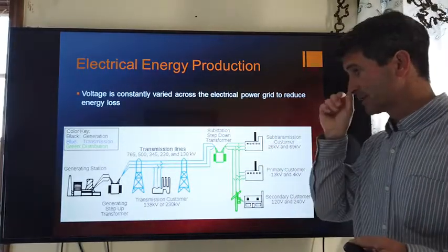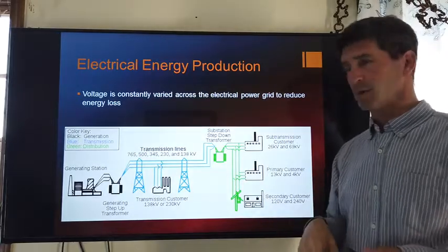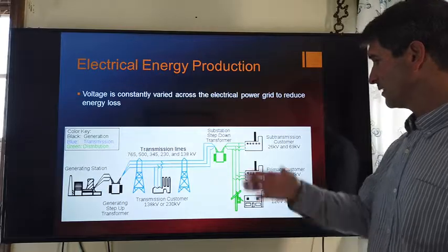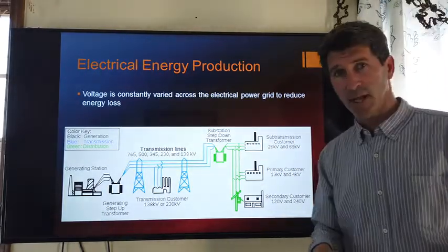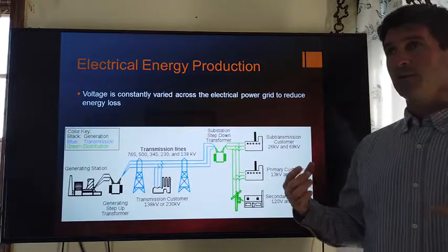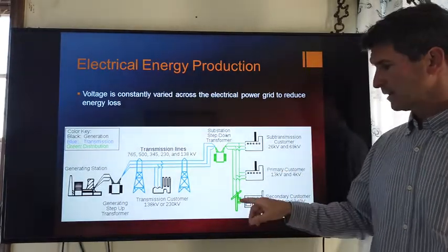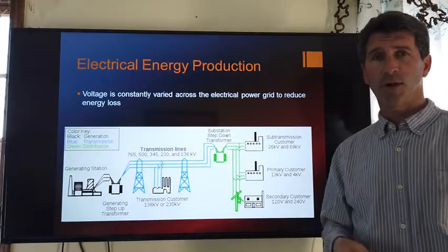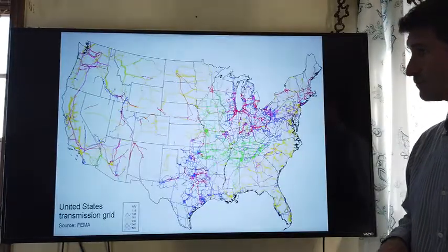So by the time it gets to wherever we're sending it, like a small town, there'll be a substation there. It'll drop the voltage to a few tens of kilovolts. It rides on the top of the pole, probably to the outermost customers at about 5,000 volts. Those little transformers that are on the telephone pole, they'll then drop it to about 120 volts. That goes into your home.